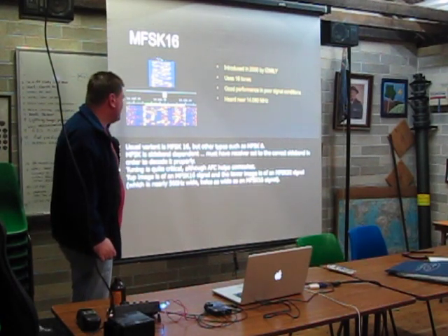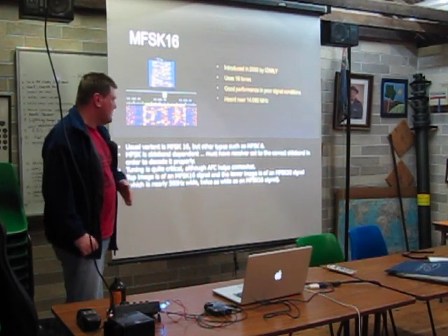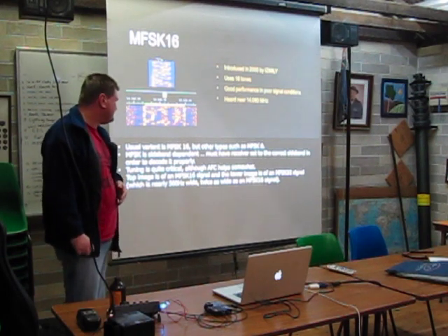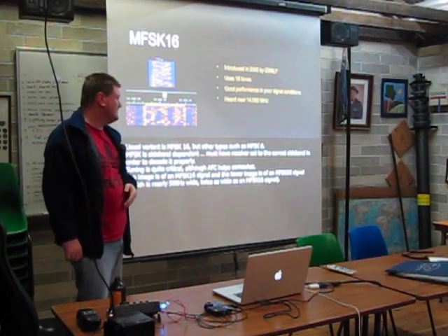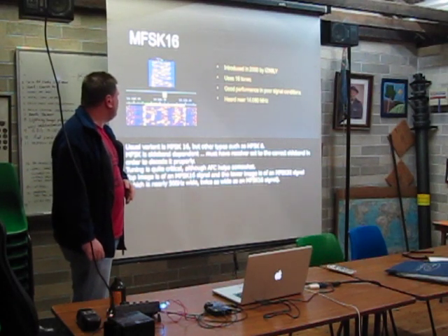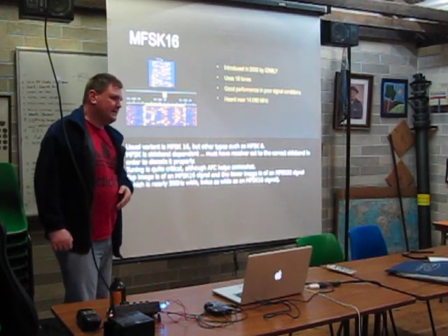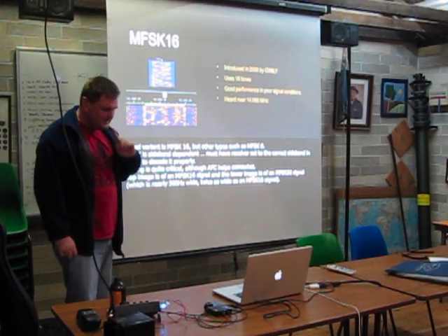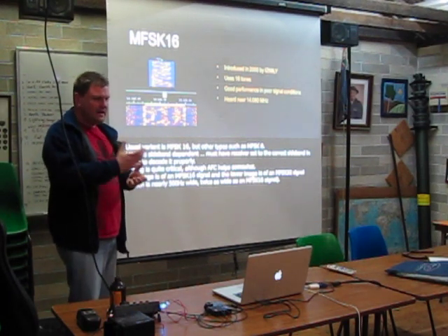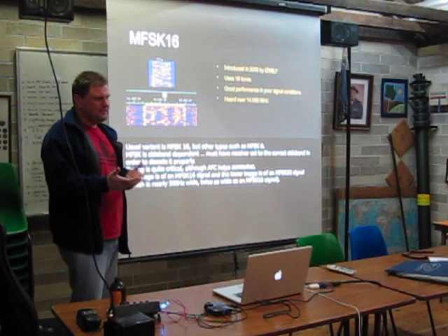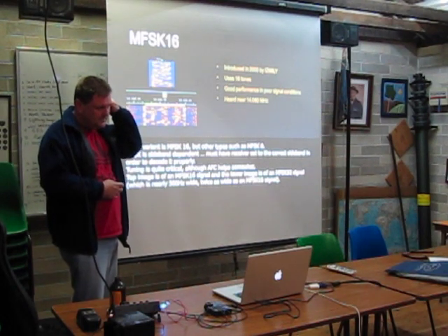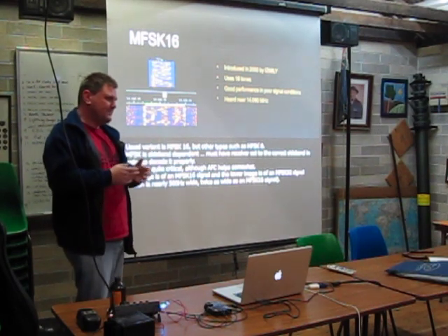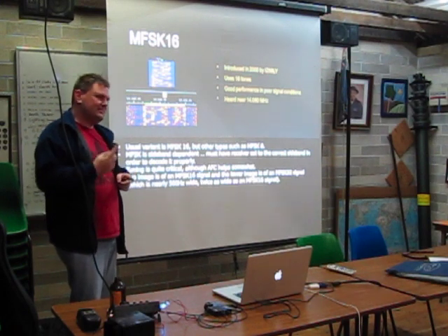So there's quite a number of different modes which are based around this multi-tone frequency shift keying, and we'll talk about some of the others a bit further on. One good thing about frequency shift keying is that your radio is only transmitting one single tone at a time. And what that means is that if your power amplifier stage isn't linear, that's not such a big issue, because if it's not linear, you can get harmonics, which you can filter out, but you're not going to get intermodulation because you've only got a single tone.